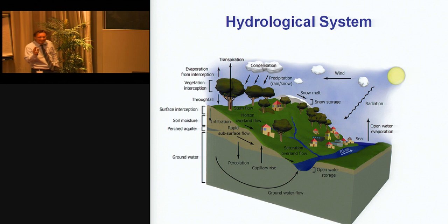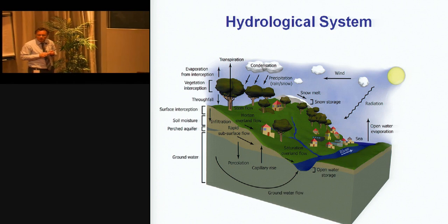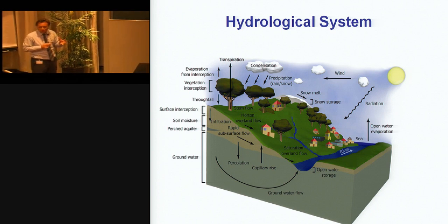One after the other, what? The depression storage, we could argue that's part of the surface storage. That's a little bit of small depression on the surface. It's part of that. But sometimes it may be useful to have a separate dS/dt for depressions, if the depressions are very important in your catchment. What else? Ground. In the ground. But we have unsaturated and saturated groundwater.